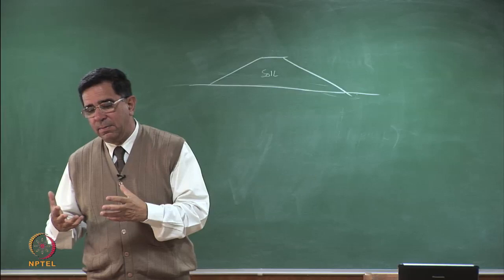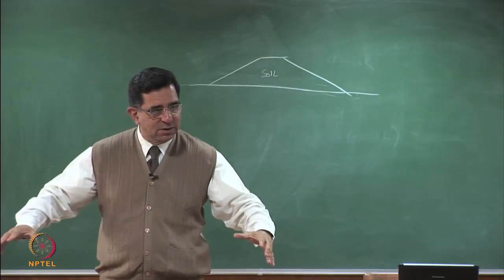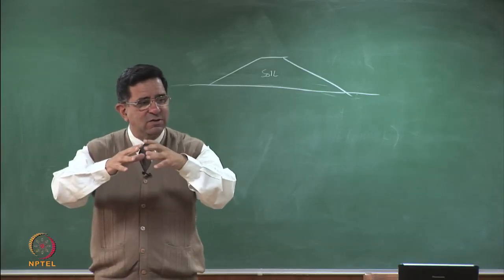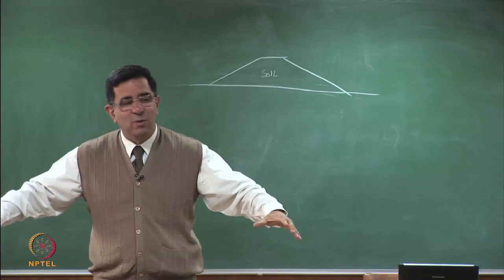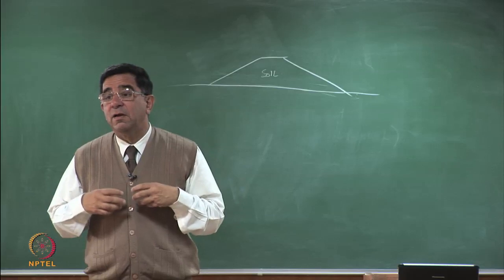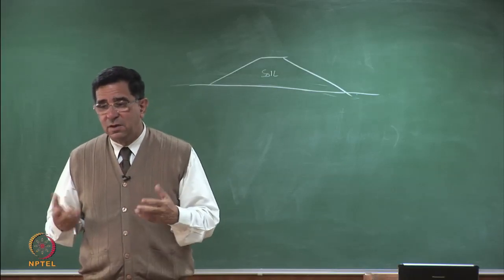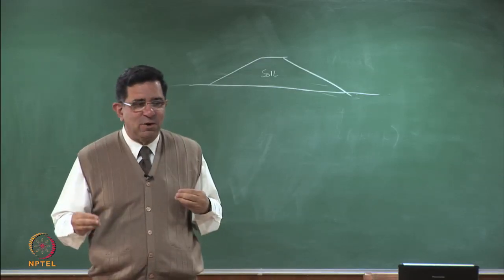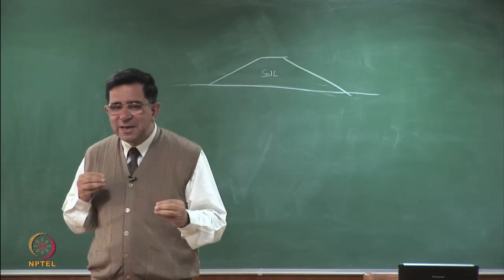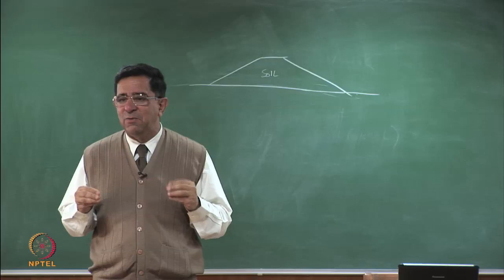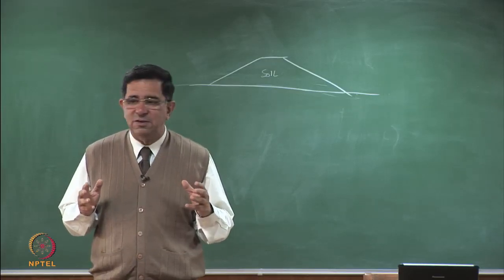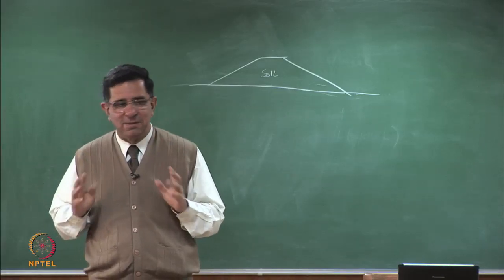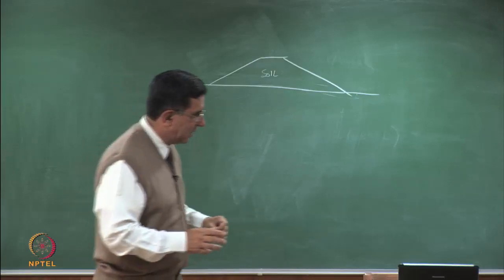So please do remember that the angle of repose tells you the phi dash of a material. Is that right? But if you have very high water content sludge, it will become very low values. Sludge, when it is dried, will have higher values. So what I am going to do is give you the values which have come out from literature, and don't ask me did they measure pore water pressure, how was the drainage, because these tests were done by waste management people in large direct shear boxes. They were not analyzed like pore water pressure measurement, B factors like we do in geotechnical engineering, but a lot of data is there, and these are the values that you get.